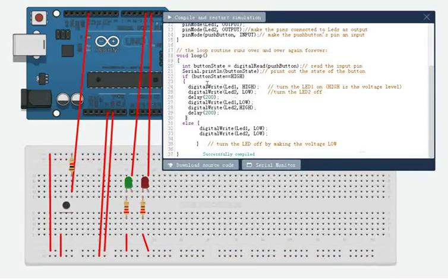You can see that this if statement is followed by a condition that needs to be verified. Then we use the curly brackets to specify which lines of code need to be executed when the condition is true. In this case, button state equals HIGH, which means the button is pressed.